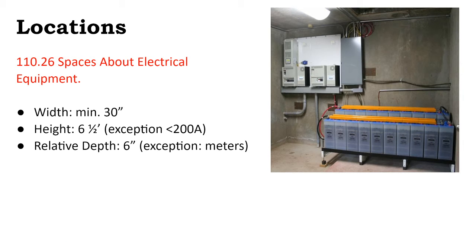The areas where people mess up is like there's a working depth requirement that's not just the workspace. So the working depth requirement is 6 inches. So there can be no more than 6 inches of space between the front of this panel and the front of this battery, because otherwise you have to lean over the battery to get to the equipment. And so there's a 6-inch depth requirement.